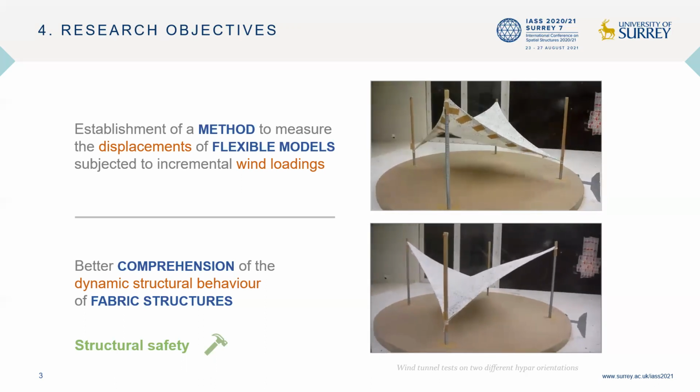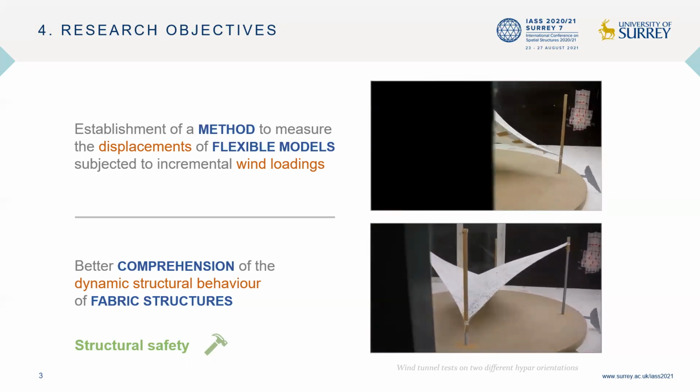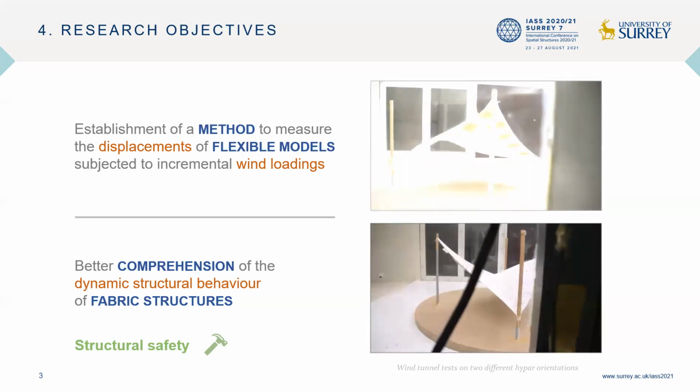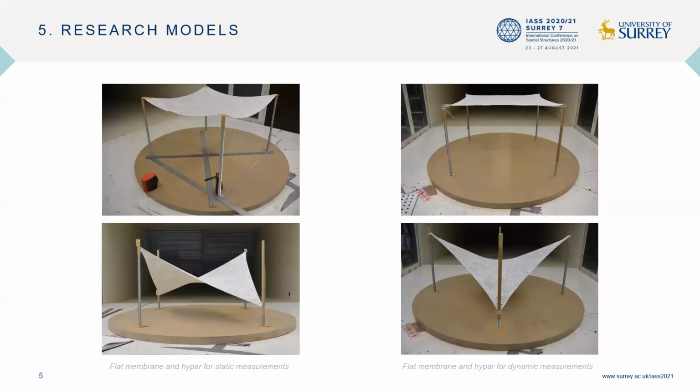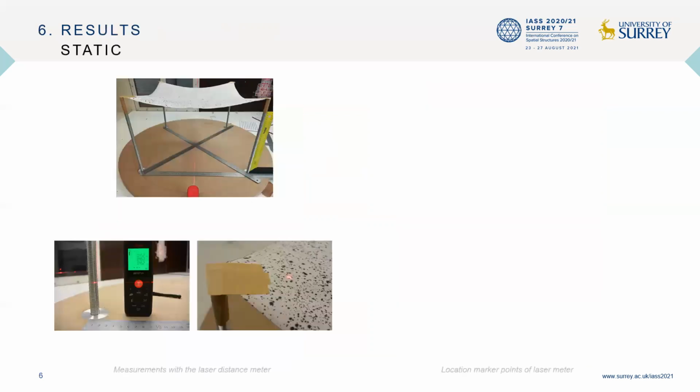Presently, little experimental work has been done on the response of fabric structures under turbulent wind loads and how structural parameters affect this behavior. Tested on stiffness, flexibility, and paint absorbance, poplin fabric has been chosen for the flat membrane and lycra fabric for the higher flexibility for the hypar. The edges of both membrane configurations have been pulled over polyamide cables, being tensioned from pole to pole.